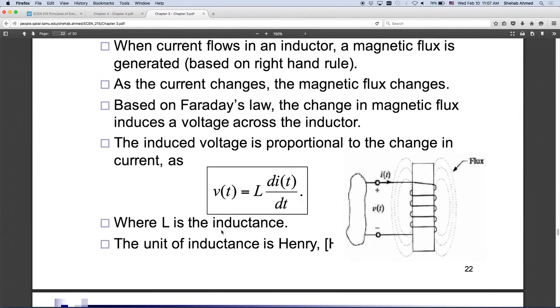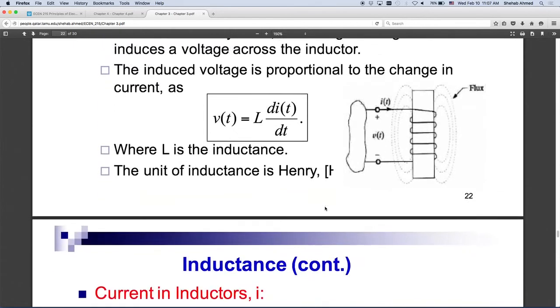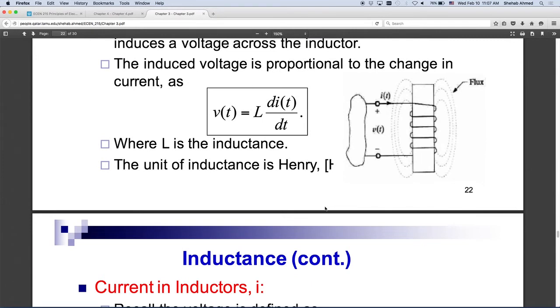The unit of inductance is H or Henry. I'm sorry, this is cut off here, but the unit of inductance is Henry. And the inductor stores energy in the form of flux created around the inductor. So you create this flux, it's storing energy. As soon as you charge this inductor, you can take it and plug it into another circuit, and this flux will collapse because you're not supplying it.